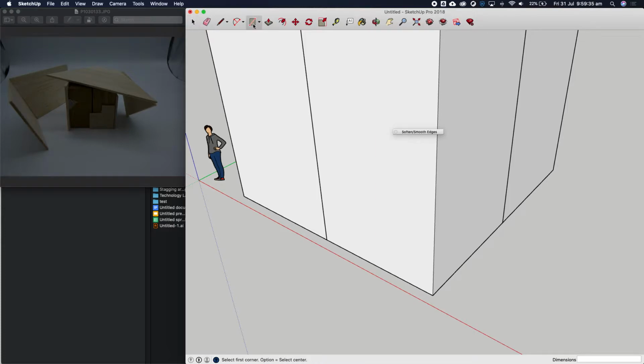We're going to create that shape on the front. So come over here. Now it's green. See how my icon turns green? That means I can modify this face. So wait until it's green. Just keep moving your mouse around a little bit till it goes green. Click, and then drag up. I'm going to make something about here somewhere. It should jump to a middle intersection. So let's go here, for example.